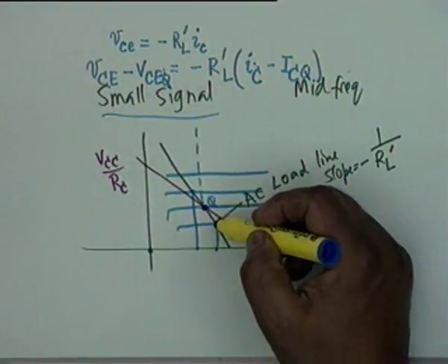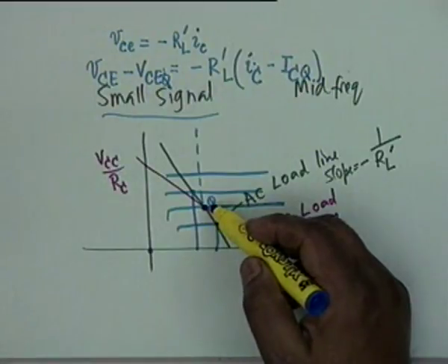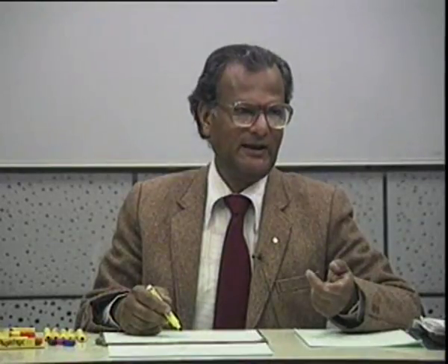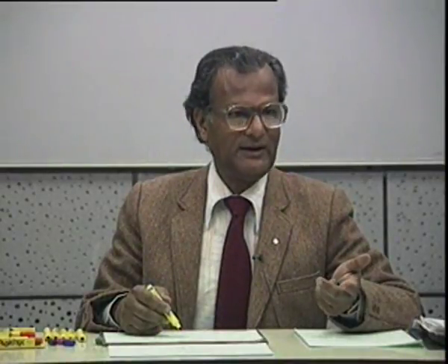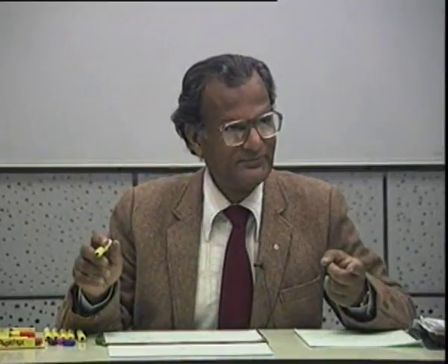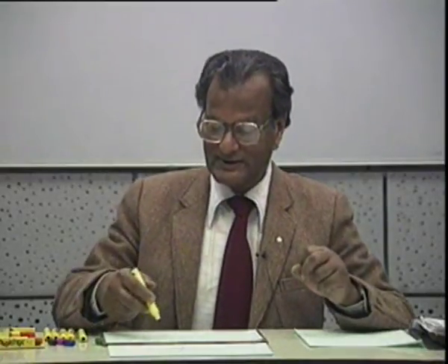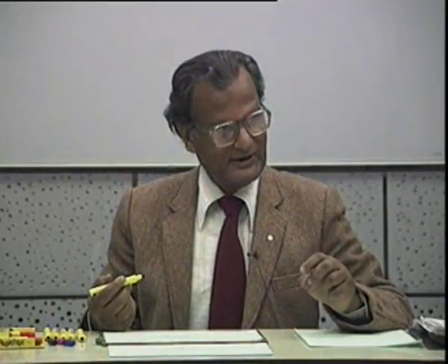If the excursion is small, then equal increments of IB will cause equal increments of IC and equal swing of VCE, and when the incremental base current is 0, the incremental collector current is also 0, and therefore it is a linear system. It can be treated as a linear system, although the transistor itself is a highly nonlinear device.